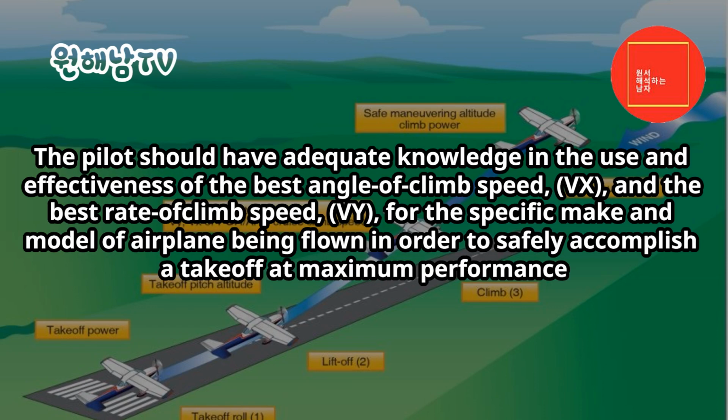The pilot should have adequate knowledge in the use and effectiveness of the best angle of climb speed (Vx) and the best rate of climb speed (Vy) for the specific make and model of airplane being flown in order to safely accomplish a takeoff at maximum performance.